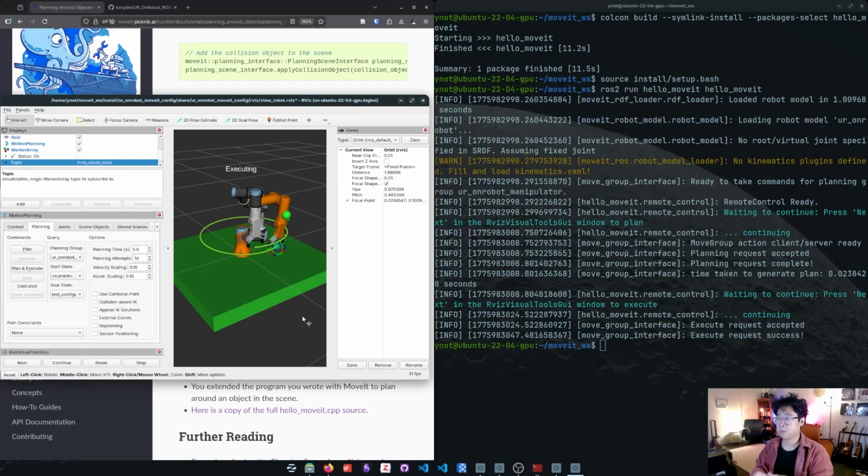So what if you want to construct a pick and place motion? As you can see, every time we use MoveIt to plan for a motion, the planner will spit out different solutions, right? And if you set up your planning scene with more constraints, maybe the motion will be more predictable, but you can't really rely on that.